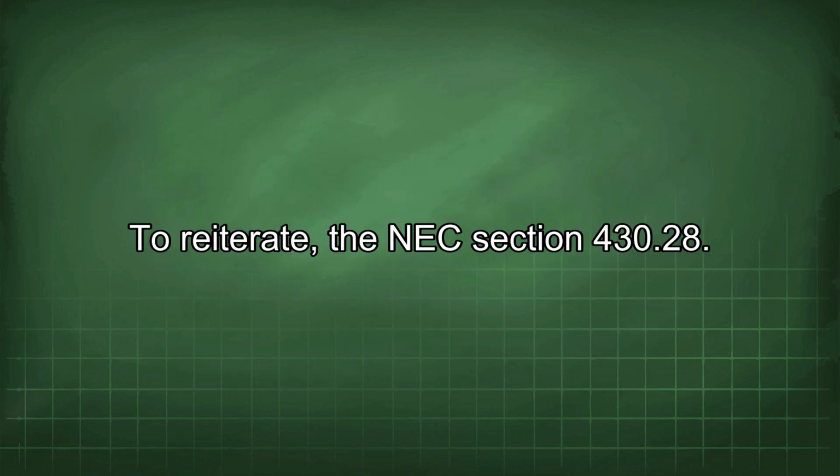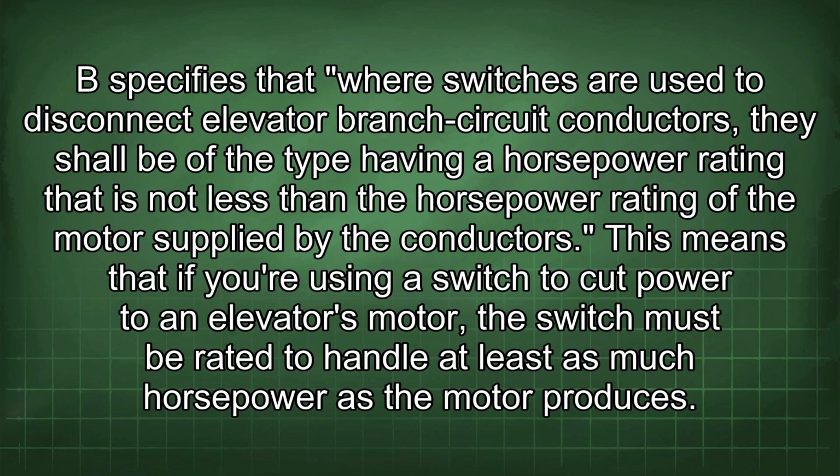To reiterate, the NEC Section 430.28.V specifies that where switches are used to disconnect elevator branch circuit conductors, they shall be of the type having a horsepower rating that is not less than the horsepower rating of the motor supplied by the conductors. This means that if you're using a switch to cut power to an elevator's motor, the switch must be rated to handle at least as much horsepower as the motor produces.